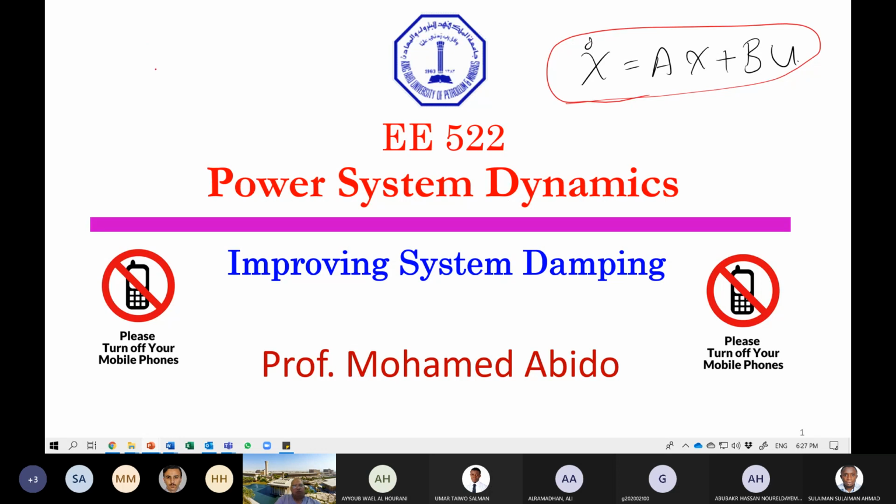So how to increase the damping now? Of course, as we mentioned earlier, we can have a power system stabilizer. But in order to design an effective power system stabilizer, you have here K (1 plus sT1) over (1 plus sT2). How to choose T1 and T2?